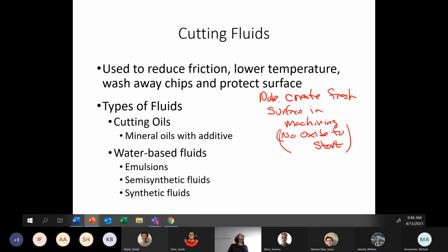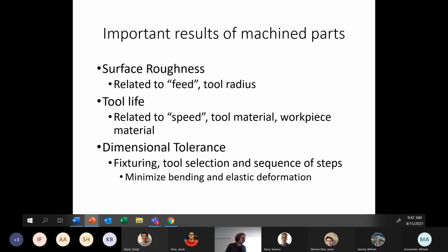If you have fluid that's sitting around, you may also have some things in those fluids to prevent mold from growing. So we do sometimes see that your fluids are slightly different. I see the biggest difference in cutting fluids between cutting metal and cutting wood. You usually don't want to combine those two. But we almost always are going to have cutting fluids in our process.